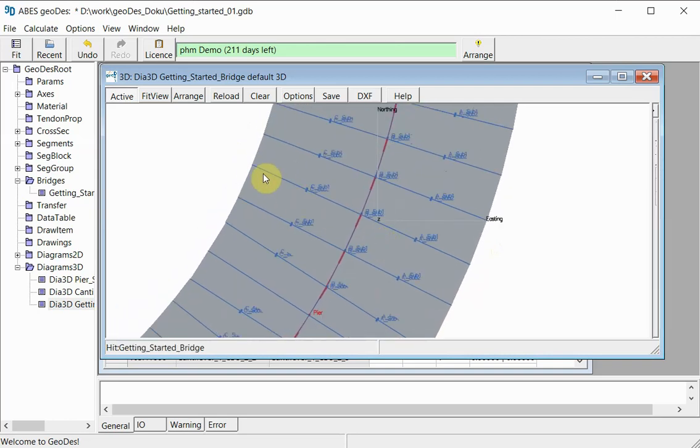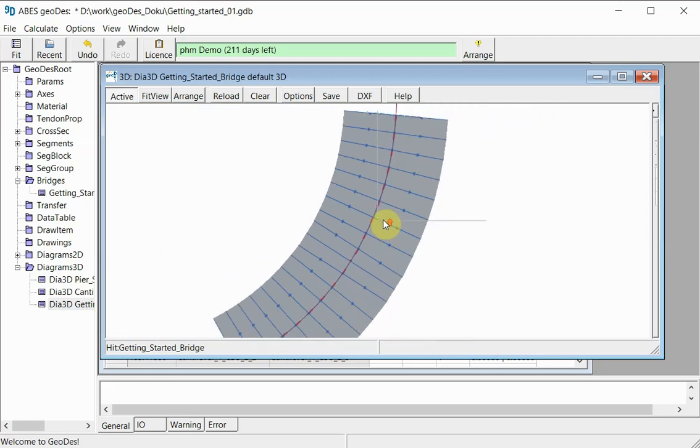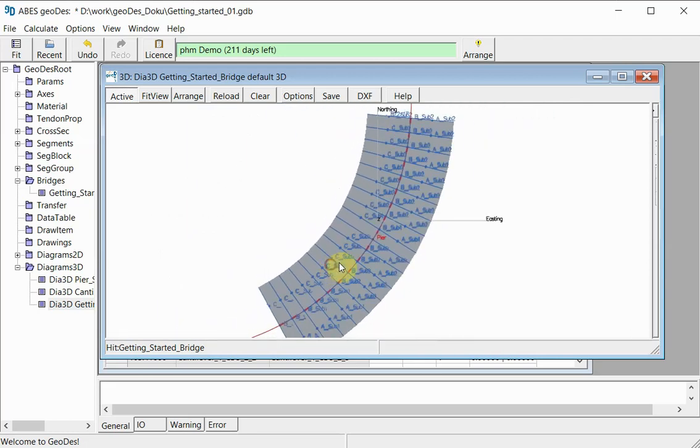And same goes for this segment here. Again, the bulkhead is on this side here. We have right angles on these sides here, and this side here will be match cast against this segment. And so the setup here is actually quite complex, even though we have a very simple example. Each segment is now already calculated and drawn up in a way that can be produced in a casting yard.